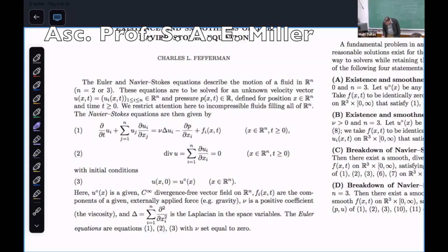But here it is. This equation here is a divergence of a velocity field. And we call this the D'Alembert equation in the business because it was created by D'Alembert. And this equation is conservation of momentum. I think I won't explain the notation. I normally would. Is it useful? Or I think most people in this audience probably know it. Okay, good. This is just a time derivative of velocity. This we call the convection term. It's nonlinear, unknown velocity, differencing in space. This term here is viscosity. This is your pressure gradient term, and this is your body force term.